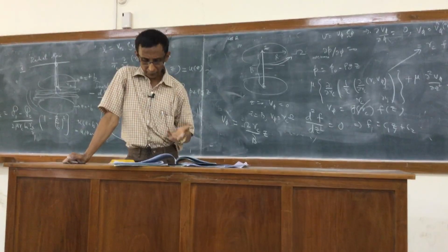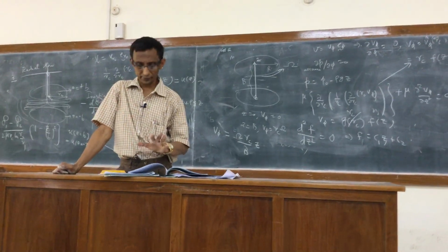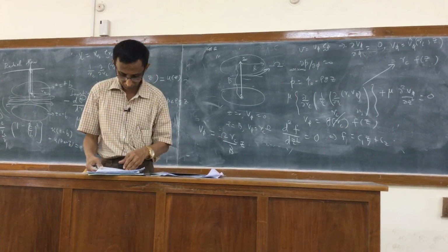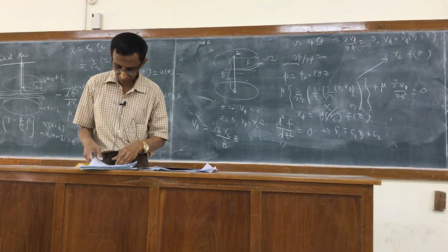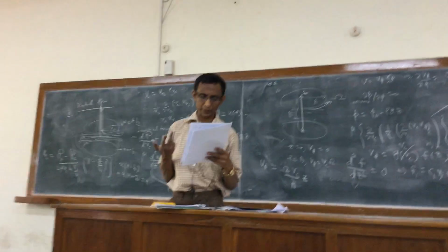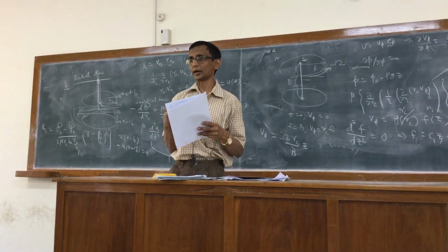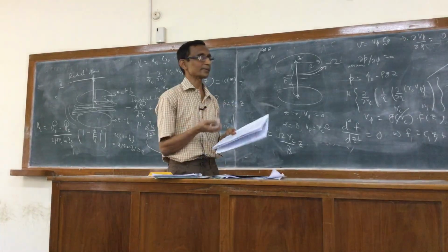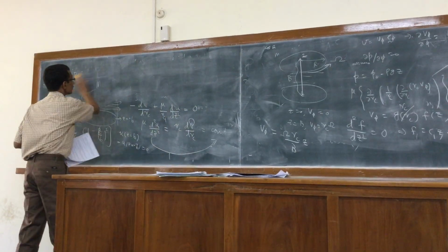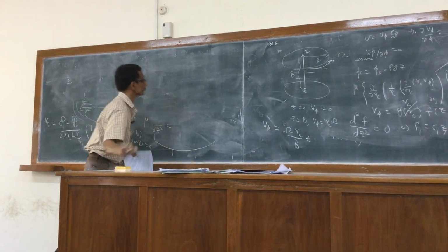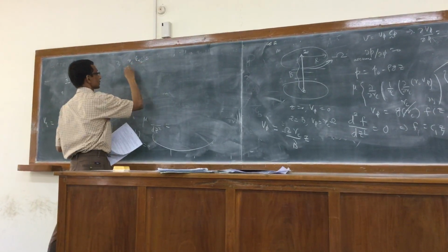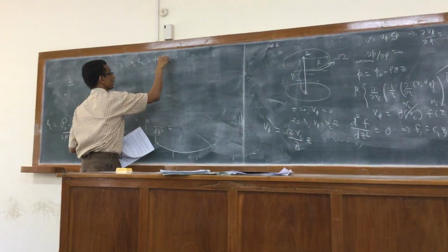Right? Now the third problem, radial flow between porous cylindrical shells. Again, I will let you do the problem. Right? Here again, the assumption that Bird is asking you to make is v_rc is independent of phi and z, and that's not what the continuity equation says. Continuity equation only says that r_c times v_rc is actually a function of phi and z. Third problem in assignment 4.